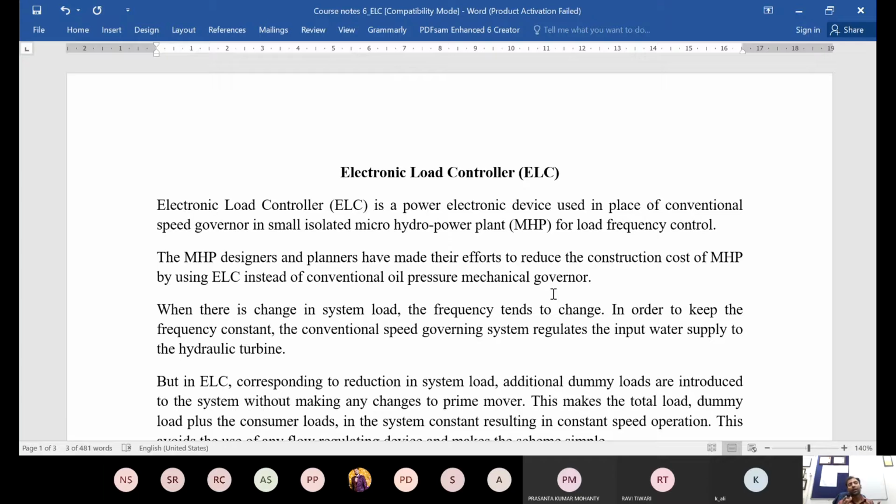The basic idea behind any electrical power system, as I think everyone appreciates, is that storing electricity at bulk size, on a megawatt scale, is not really economical as of now. Battery technology is not really up to the mark in that sense. So a major component of the challenge of power systems is to balance the load and generation. The governor mechanism is one such mechanism which helps match the generation with the load on the system. That is obviously the best way and is considered the standard way of doing it.